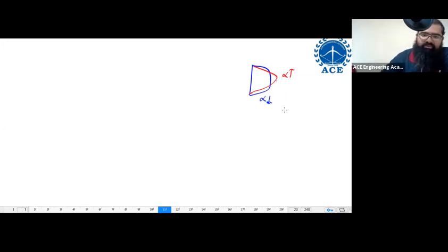In laminar flow through pipes, you are going to have a parabolic velocity profile. Variation is very strong. In turbulent flow, the variation is not that strong. You are going to have a logarithmic velocity profile, which looks almost like a rectangle. This is your turbulent flow, and laminar flow will be something like this. Now, stronger variation in laminar flow, therefore alpha is higher over here and lesser over here. This is the reason why laminar flow is going to have a higher value. Don't worry, you'll understand these things once we go into that topic.